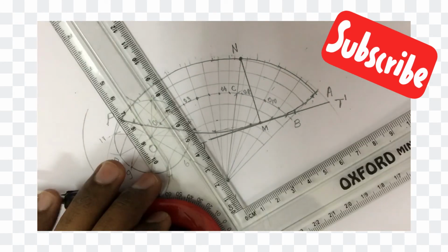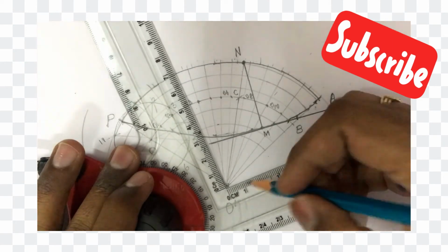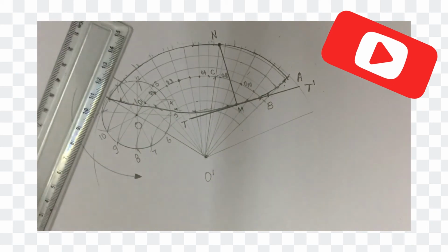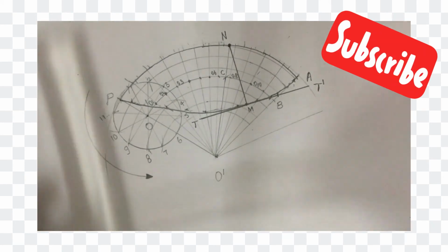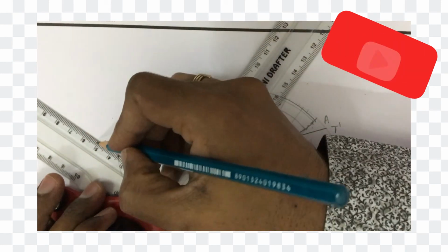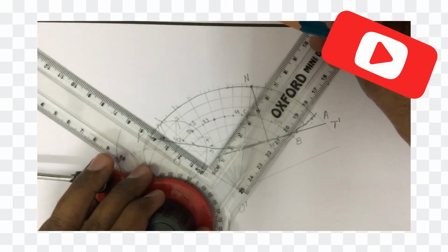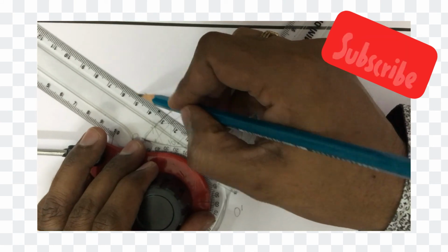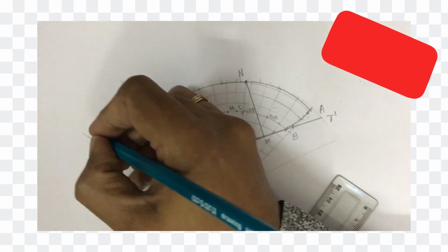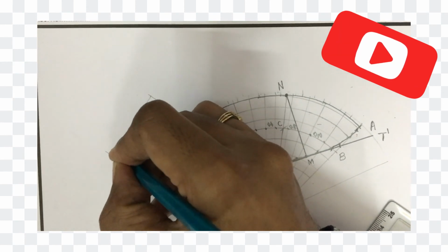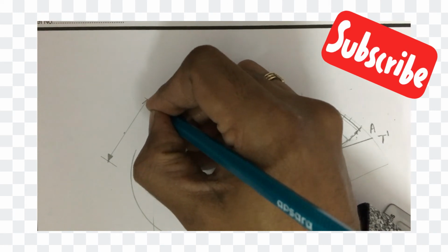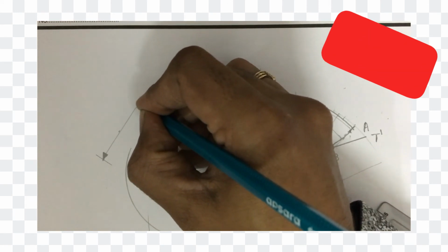And later we are supposed to furnish even the radius of this. The directing circle is given. And do not forget writing the dimensions of this. I am writing here, for example, let it be. So this is the dimensioning whichever is given in your booklet. You are supposed to work out the dimensions of that. This is the dimension line. And fill it, closed and filled arrowheads, very neat in size. And your lettering and numbering to be done only in HB pencil.